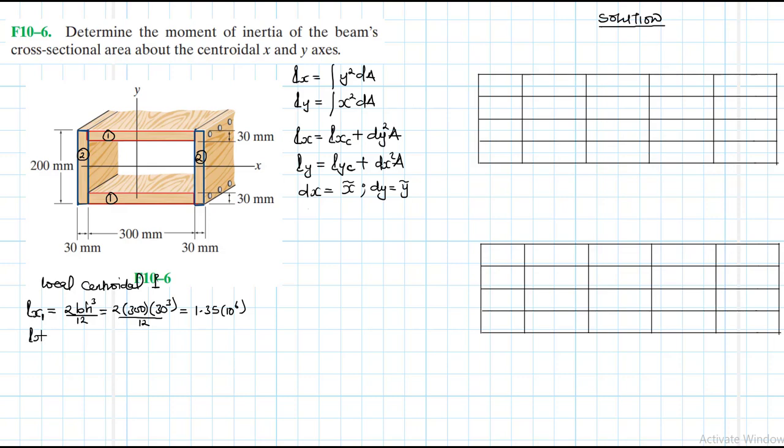Then moment of inertia for part 2. Also there is symmetry, so multiply by 2, bh cubed divided by 12.